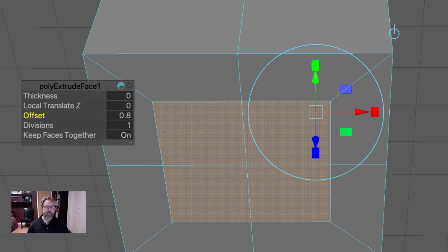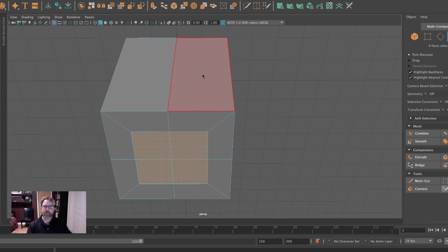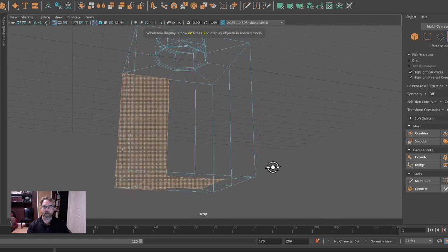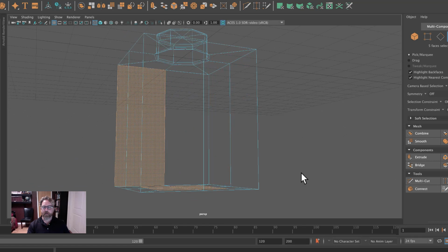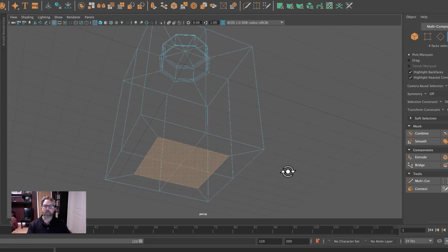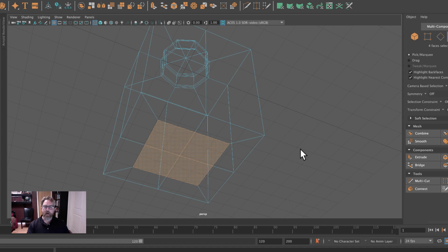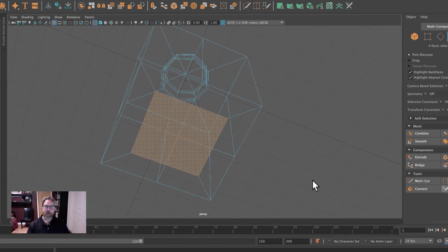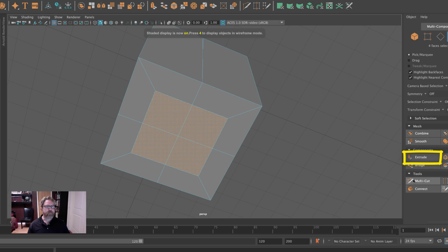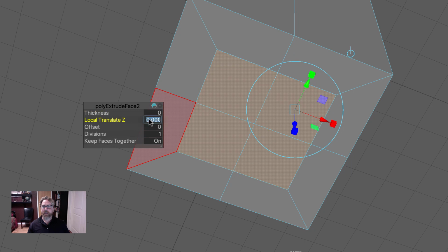And now we're going to extrude again. If you accidentally had clicked off, or maybe you're coming back later after you've saved and you're picking it up here, you would just need to reselect those faces. And again, I'll hit 4. And that time I did accidentally select something on the other side. So an opportunity to demonstrate Control, bounding box select, and that will deselect while maintaining what wasn't beneath that bounding box selection with the Control key. All right, we've got that selected. I'll go ahead and hit 5 since we verified. And we'll hit extrude. And we're going to move this one on the Z, and this will be negative 4.